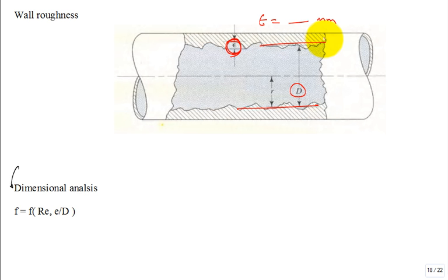And what we find is the friction factor, dimensionless pressure loss, is proportional to the Reynolds number, how fast the flow is going, if it's going to be laminar or turbulent. But now we're all turbulent. It's really how fast is it going, and how rough it is compared to the diameter. It's epsilon over d, the relative roughness. This is dimensionless, this is dimensionless, this is dimensionless.